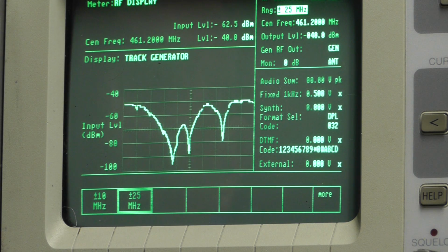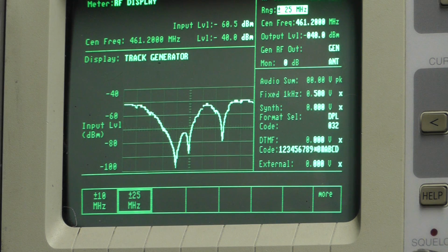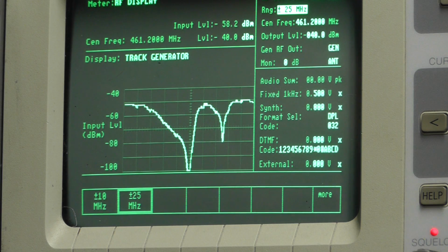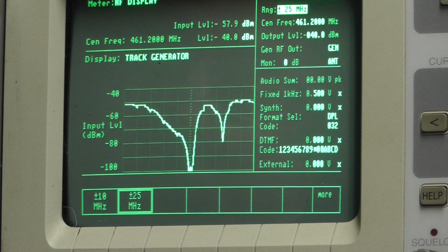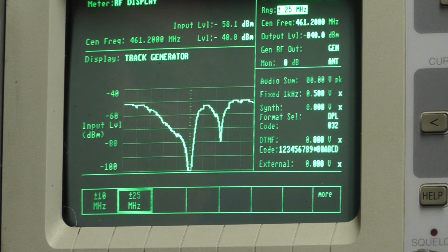That lower one there, as I turn it back and forth, seems to be moving. That seems to be the notch associated with this, the resonant frequency associated with this cavity. We'll get that down close to where our frequency is in the center there. This next one, let's see where that one is. I see a notch there. That notch appears to be associated with this cavity. Let's see if that is a notch associated with this last cavity. Indeed. And carefully tune that there.